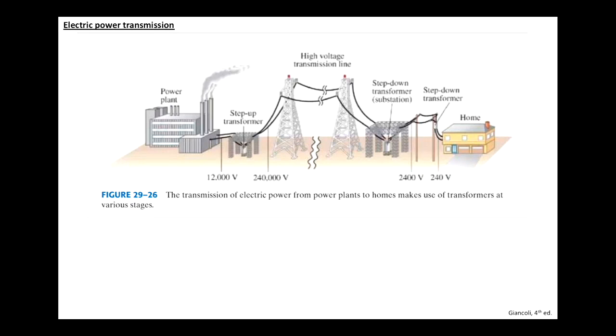On the other hand, if I step up in voltage and drop the current, I can transmit a high voltage, low current signal, and since the current's low, I'm not going to lose as much in the transmission over those many miles. Then I do the exact opposite at the end and drop the voltage, which will increase the current to what I need it to be.